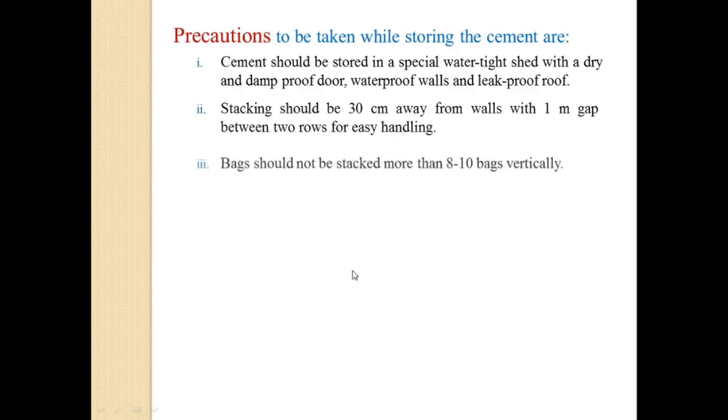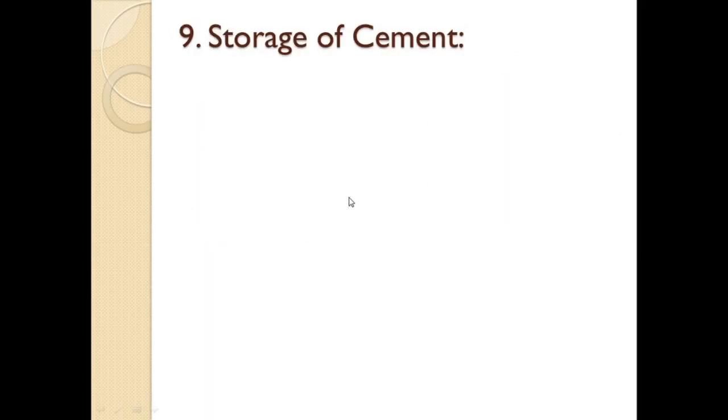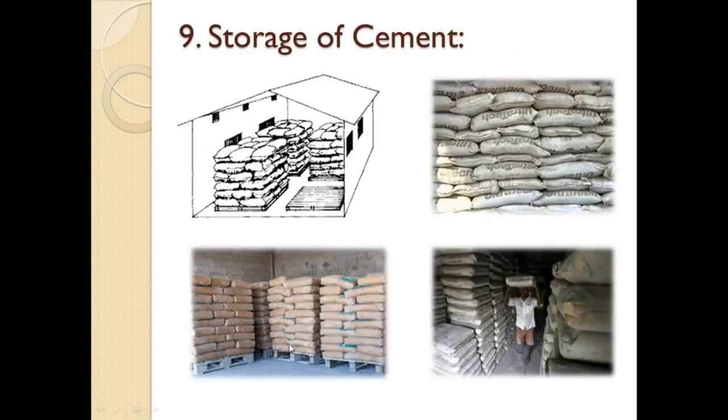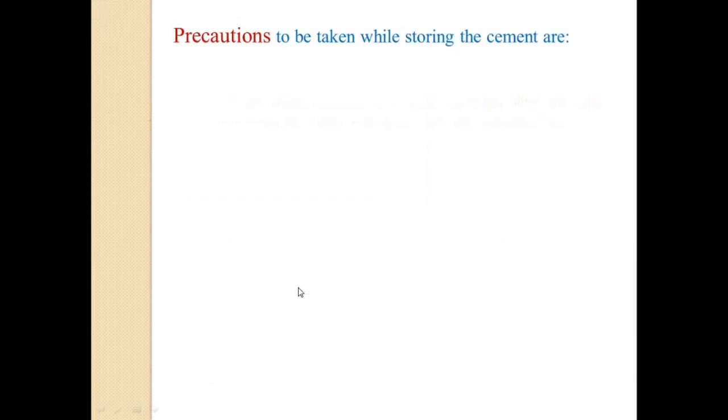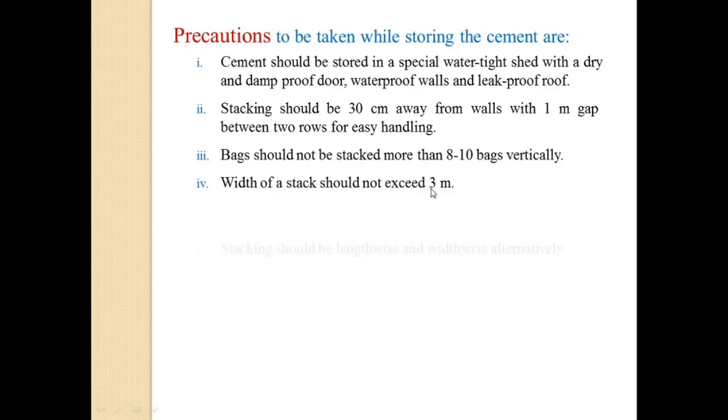Next, the bags should not be stacked more than 8 to 10 bags vertically. Here we can see the bags. These bags should not be stacked more than 8 to 10 bags high. Next, the width of the stack should not exceed 3 meters. One stack width should not be greater than 3 meters.